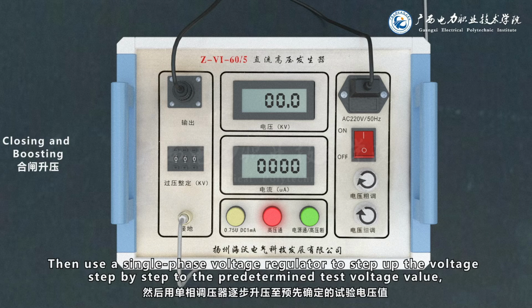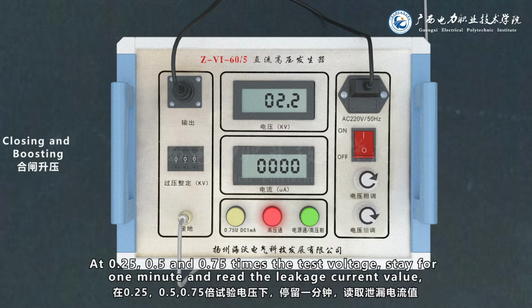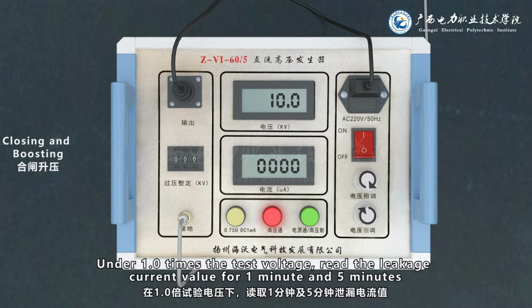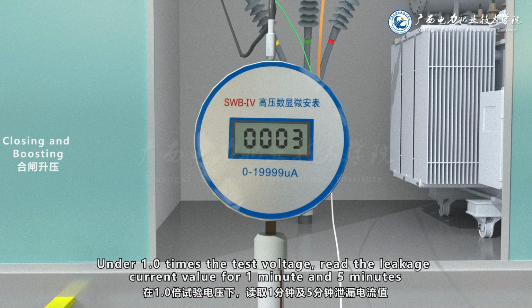Then use a single-phase voltage regulator to step up the voltage step by step to the predetermined test voltage value. At 0.25, 0.5 and 0.75 times the test voltage, stay for 1 minute and read the leakage current value. Under 1.0 times the test voltage, read the leakage current value for 1 minute and 5 minutes.